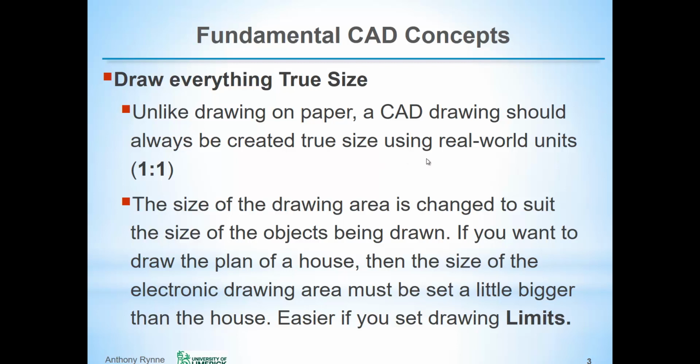Now, while you don't need to set the limits of your drawing, I would recommend that you set the limits so that you can use the grid and the snap easier for the size of whatever you're drawing. So if I'm drawing the plan of a house, then I would set the limits of the drawing slightly bigger to accommodate the house, and you can always change the limits as you go.